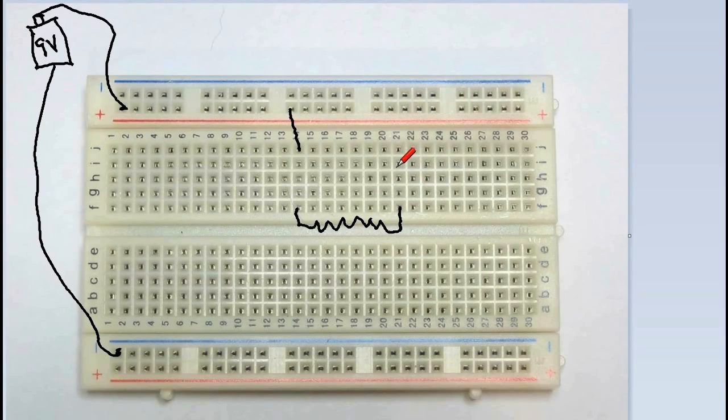Okay, so now I take my LED and I plug it in here. And let's bring it up. Let's make our little LED. We're going to use this schematic symbol eventually for LED. And then I plug this side in here. Now these two are not connected, so we're still not getting any light. Now this comes all the way across here. Now what I could do is take any one of these holes and run it right over to the negative, and then we would light up.